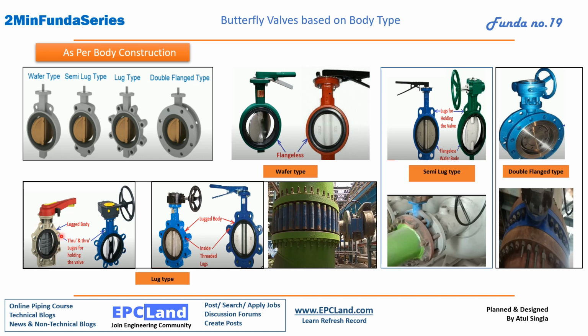Sorry, this is through bolt points and we are having lugs here. We can handle it from these points, and we can bolt it through these holes. If you see the actual picture, these are the lugs and studs are moving through these lugs and we can bolt it on both sides. So this is just a pictorial view of lug type. Same is the double flange type. We are having two flanges on both sides of the valve and the bolting arrangement will be like this. This blue flange is the flange which is a part of the valve and these brown ones are the connecting ones, and we are having bolts this side, bolts this side, again this side and this side. This is a very heavy design and again it is having two flanges, so it is a costly design also. So all these are the valves which belong to this category, which we have categorized based on the body configuration.